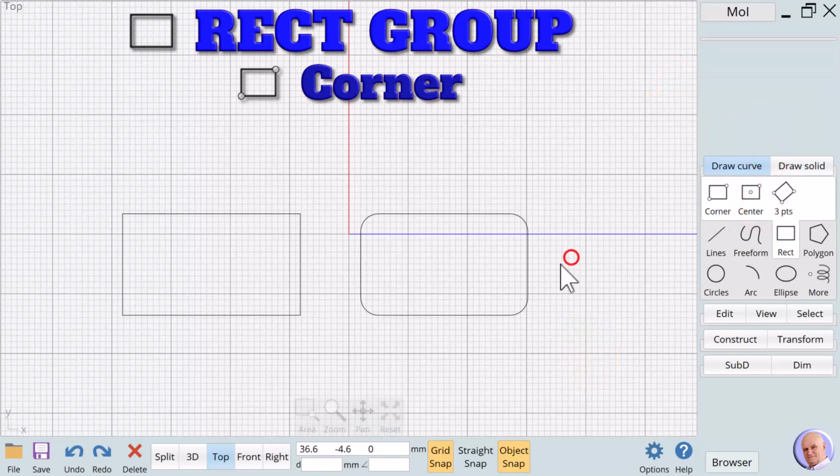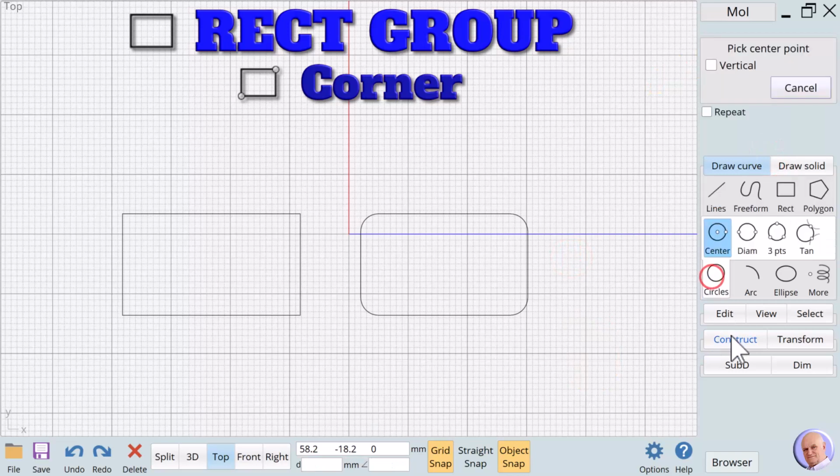With both types of rectangles complete and Object Snap turned on, the different snaps that are available with the regular and rounded rectangles can be demonstrated. With the regular rectangle, we have end, on, mid, and center snaps. The center snap is located in the center of the rectangle. With the Rounded Corners rectangle, the center snaps are located at the center of the radius of each rounded corner, but there is no center snap for the entire rectangle.